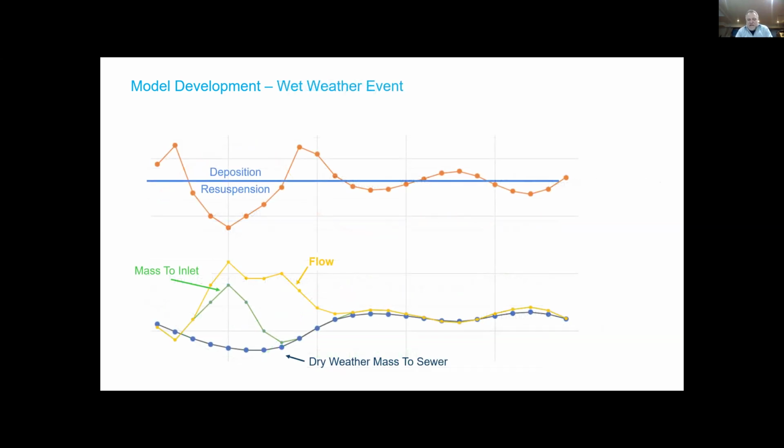So if it rains, the underlying intuitive model that I'm thinking about developing is that you get this resuspension. Whether it's raining overnight or raining during the day, you have more force on that material in the sewer, and you're scrubbing some of that material into the treatment plant, and therefore you're getting this variable influent. And because that material is digesting in the sewer, you're also able to model this variable characterization. So now all of a sudden your ammonia to TKN ratio is changing, and your solids is changing, and your VFA portion of your incoming COD is also changing, depending on how long that material has been sitting in the sewer.